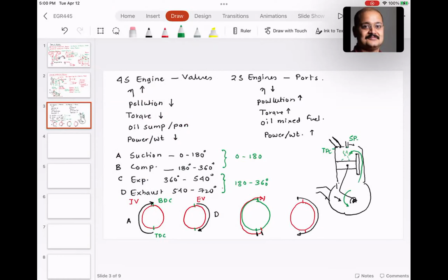In the 2-stroke engine, usually on the intake side, the oil is sprayed into the charge. And that's why if you see those leaf blower engines, you don't have a separate oil cylinder or separate oil sump. You mix the fuel and oil together and then basically run those engines, because the oil is pre-mixed.